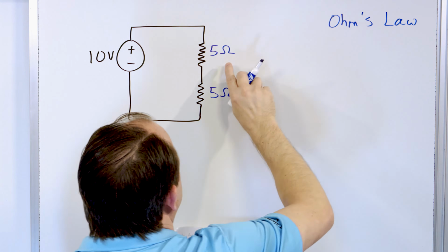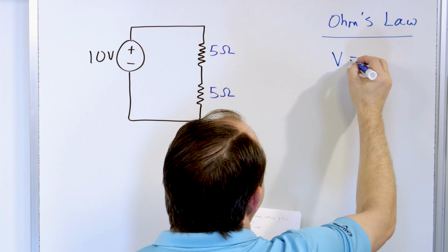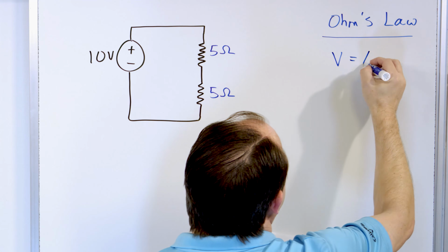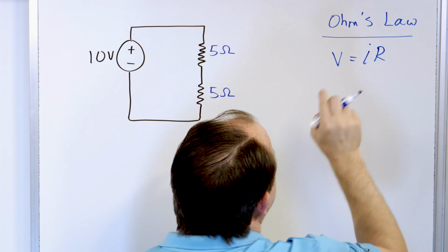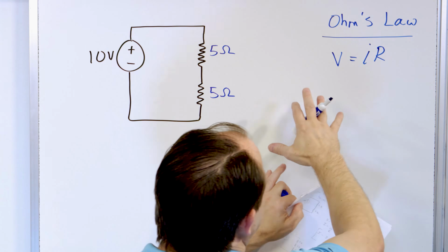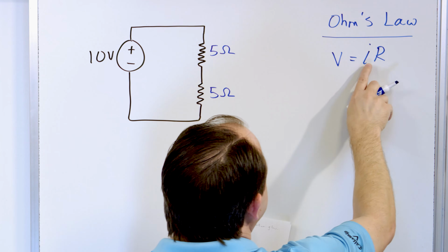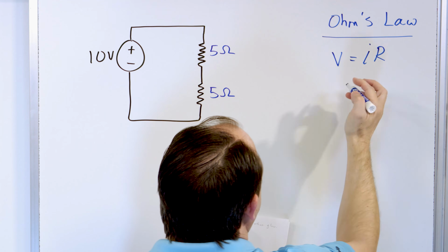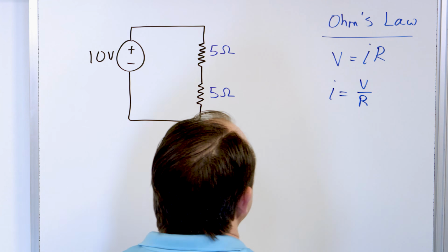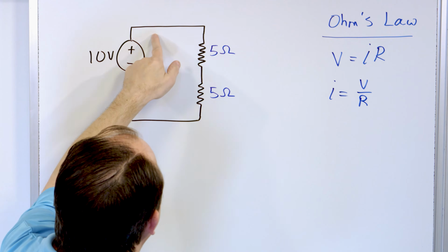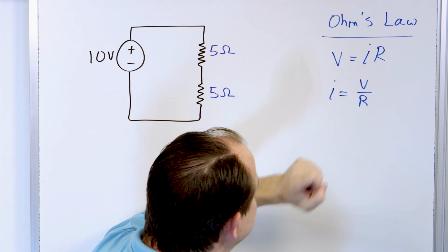Same ohm as this unit here, Ohm's law. And Ohm's law is that the voltage across any circuit element is equal to the current flowing through it multiplied by its resistance, if it's a resistor: V = I × R. This gets more complicated for alternating current later on, but this is the basic idea. So if you use algebra to solve for I, just divide both sides by R, you'll get I equals V over R. Right? So what this means is that the current flowing through the circuit gets larger if I give more push with V on the top.